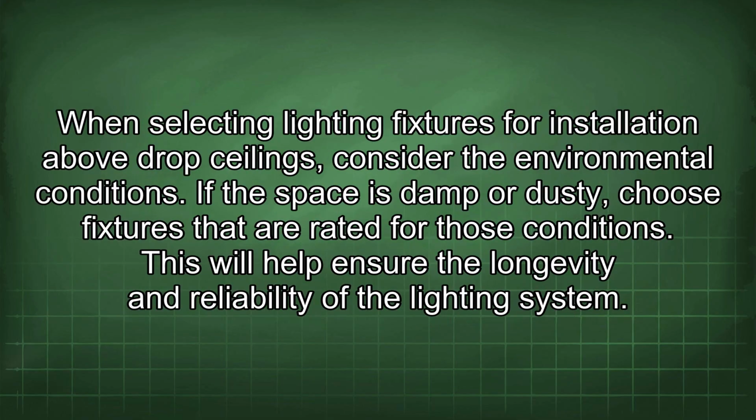When selecting lighting fixtures for installation above drop ceilings, consider the environmental conditions. If the space is damp or dusty, choose fixtures that are rated for those conditions. This will help ensure the longevity and reliability of the lighting system.